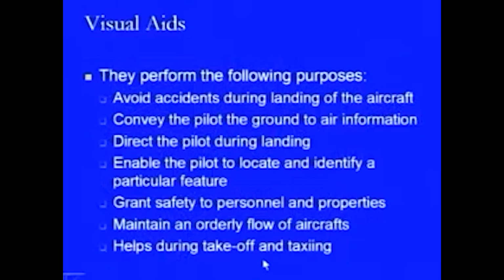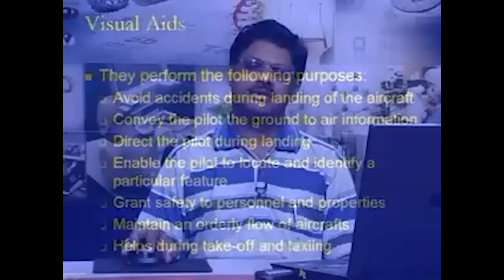And it also helps during takeoff as well as during taxiing, because the aircraft which has already landed on the runway strip can understand the other markings or other visual aids being provided, by which it can move towards the exit taxiways or the taxi lanes, by which it will be going towards the storage area or the aircraft stands where they will be holding, or where they will be going towards the terminal aprons. Everything is defined in terms of the visual aids, and following those visual aids the aircraft can reach their ultimate destinations.